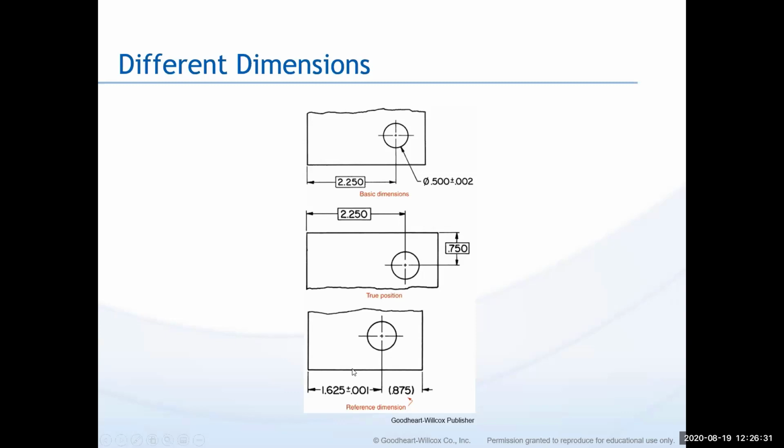And that's a very important thing, to have established datum points that you measure from, because you can end up compounding our errors, or stacking up our tolerances, so that a part, even though it seems like it fits within the tolerances and all the holes are within the same tolerance, ends up being out of tolerance completely. So what this is saying here is after we've gone over the 625 thousandths, plus or minus 1 thousandth, the leftover to this edge should be 875 thousandths.